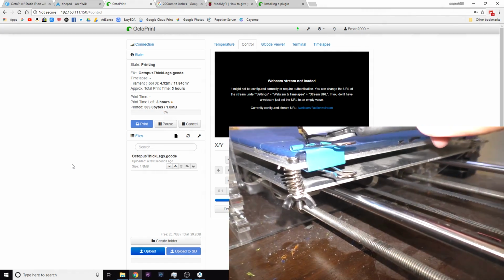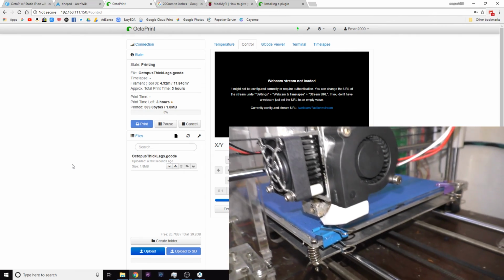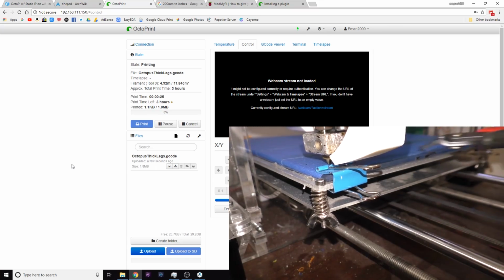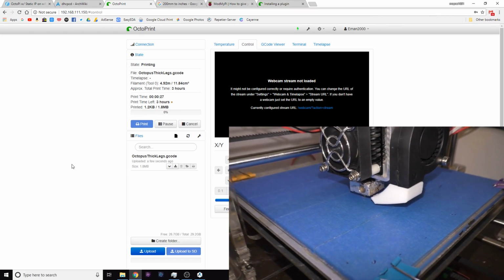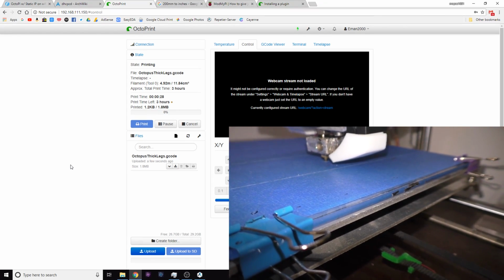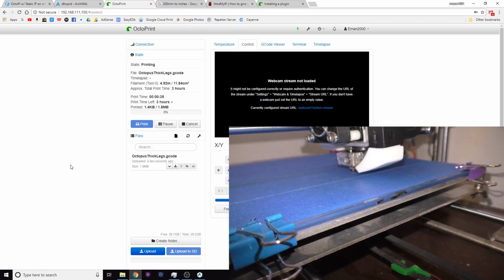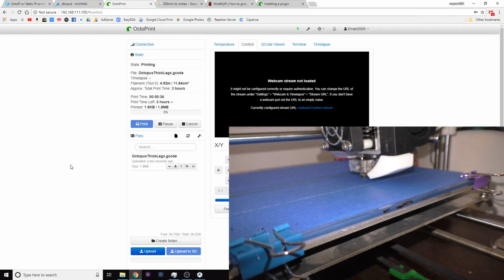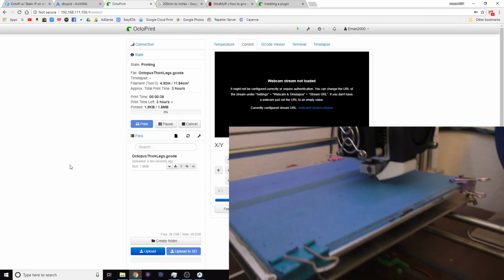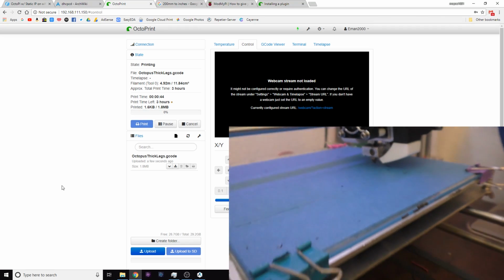I think it's going to ramp the nozzle temp all the way up to like 245 or something like that for this print. Alright, here we go. So that actually appears to be working just fine, except for I might have the nozzle height really, really low apparently. Not sure I can do anything about that, but we'll see what happens here. Looks like we're starting to print.